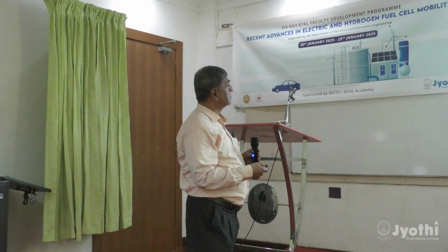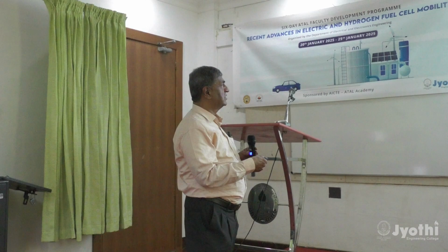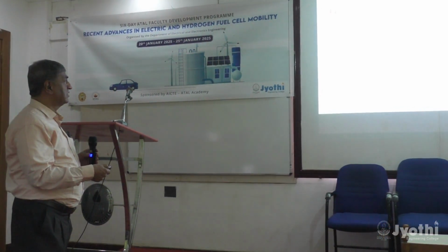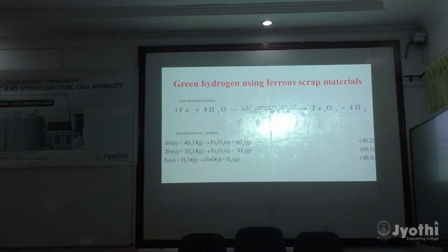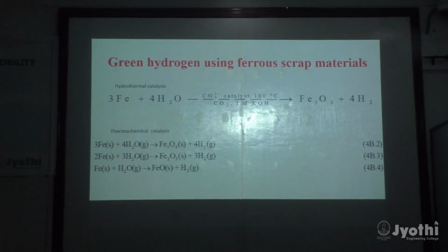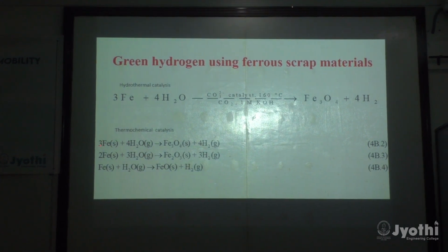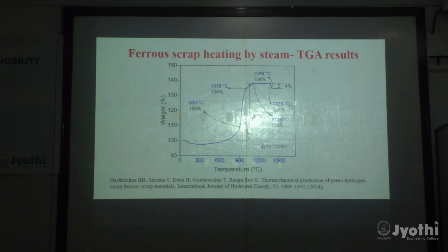There are also processes that people talk about in terms of what is called hydrothermal catalysis. In the presence of some catalyst, let us say, in a liquid medium, it is possible to produce also. This has been reported in literature, but what we have done is completely all gases only. Only iron in the form of a powder, or rather scrap, iron filings, on which you pass steam and you can produce hydrogen from it. This also, in fact, was a paper that has been published in the Journal of Hydrogen Energy.